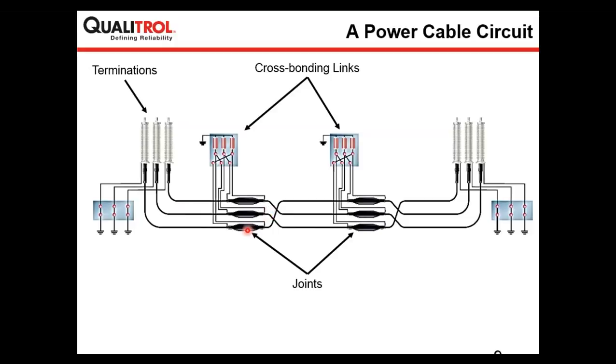In a long cable network, whether it is a transmission network or a distribution network, there can be solid grounding at the joint location. And if it is a transmission network, there can be cross bonding. The reason for doing grounding and cross bonding is to avoid circulating currents in the power circuit.